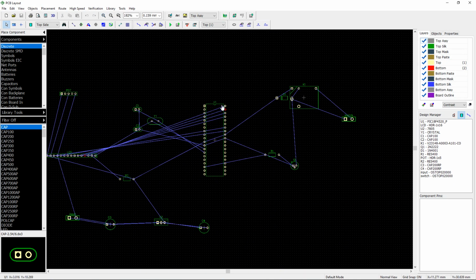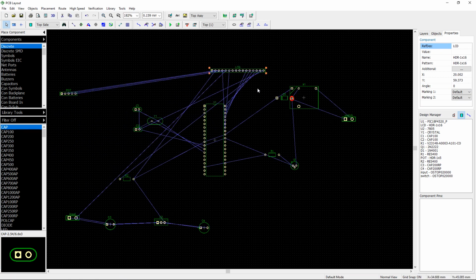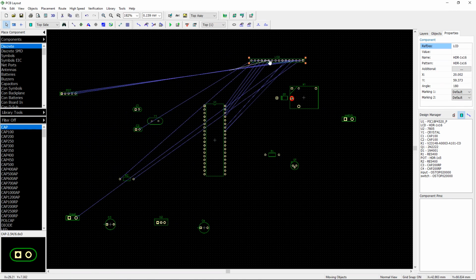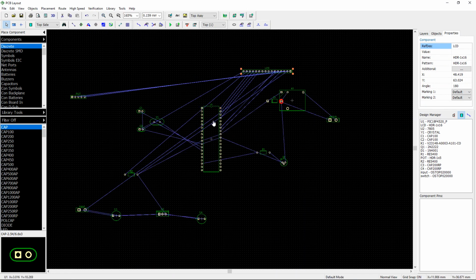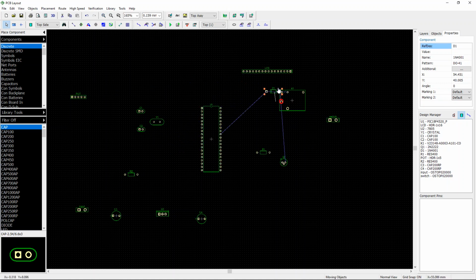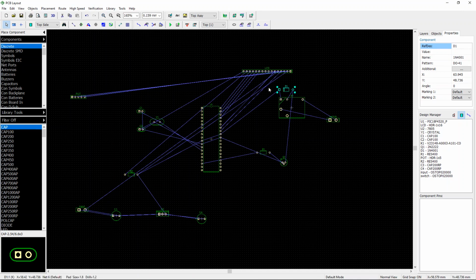As you can see, we have this feature now. These are called Ratlines. They show you where there are supposed to be electrical connections. Now say if you've just moved over to PCB here and you don't have these Ratlines, you're going to have to manually see where the connections are. And as you have noted from our earlier schematic, there was an error whereby I thought I had a connection and the connection was not there. Now imagine after completing this PCB design you think there are connections all over, but there isn't a connection. These Ratlines are there to show you whether there is a connection or not.